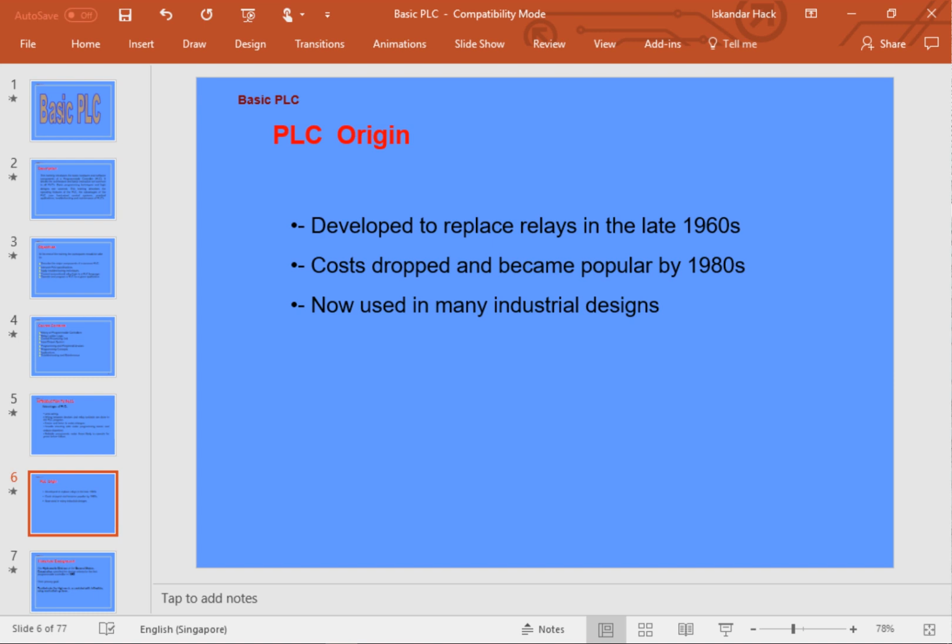If you grab an 8051 board or a Raspberry Pi or an Arduino, you have to write all the software. You have to design all the hardware interface equipment, and you're trying to run a factory floor. You're running some large motors and some large currents, and obviously a little Arduino runs on 3.3 volts. You have to have quite a bit of interface hardware for that, and that takes time and engineering talent. PLCs are quicker, but they're a little bit more money up front.